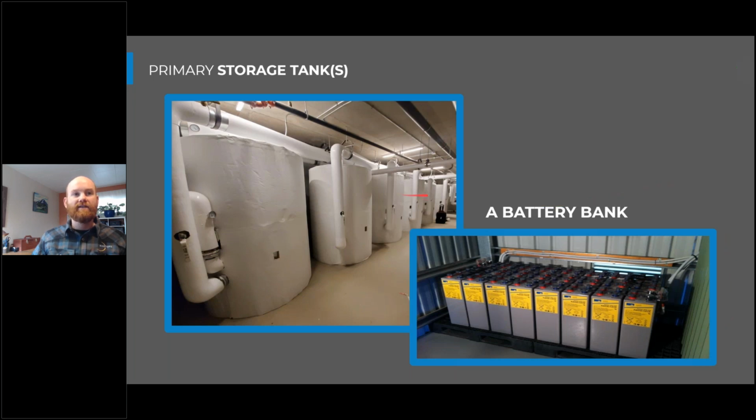And so that's why in this example, although this is maybe a 250, 300 unit apartment building, we have 6 storage tanks connected together. Each one of those storage tanks can hold about 500 gallons of hot water. And so we can use that in our favor to really reduce the amount of heat pumps we need to provide to that building, to reduce the first cost associated with that system installation.